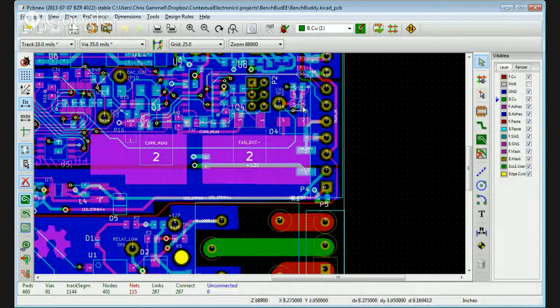Also interesting, we haven't tried attaching the temperature thing here as well, and moving forwards, we might want to. The only downside is that we're using the same op amp for all this stuff, but in a best case scenario, this heat stuff would be very isolated from all of the more sensitive measurement stuff. So we'll be able to adjust for it in terms of temperature, right? We'll be able to measure the temperature on the board, but it's still probably good to have that a little bit more separated.